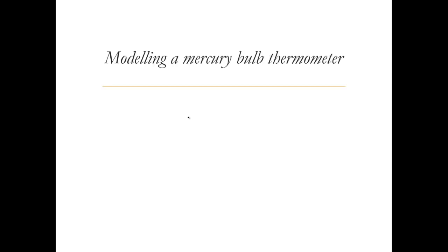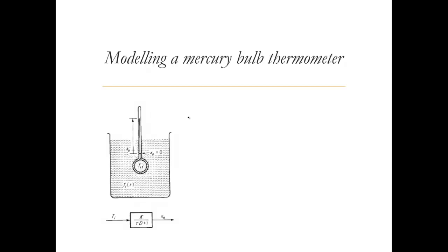And all those things. So with all those things, if we want to model such a thermometer or any other instrument for that matter, we'll have to use obviously the physics behind all these processes, and we come up with some equations in this form, where we have the temperature as the input and x naught, which is the height, or you can say the scale on this, actually tells us the output. So this is the relation that it follows, where it's nothing but a first order system equation.